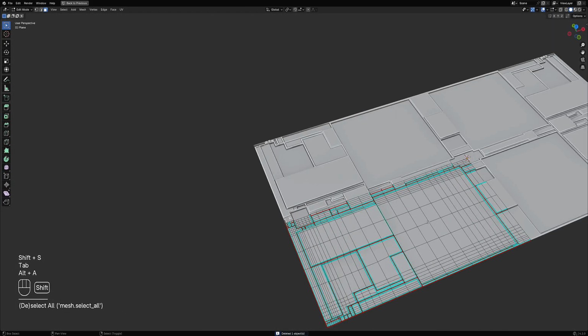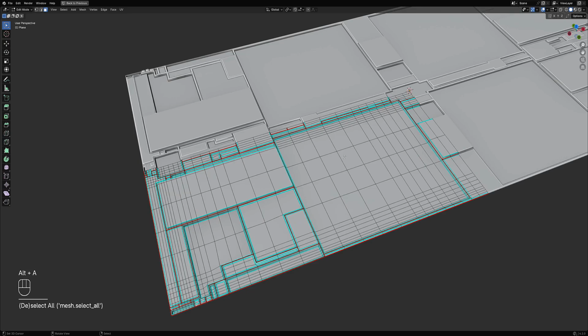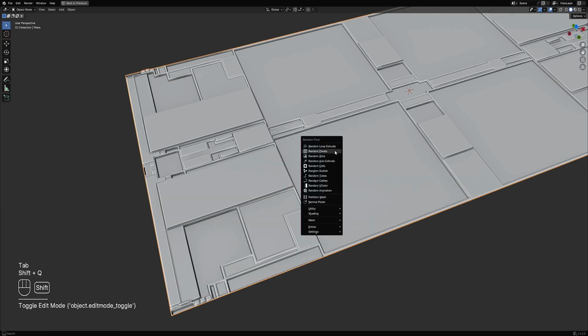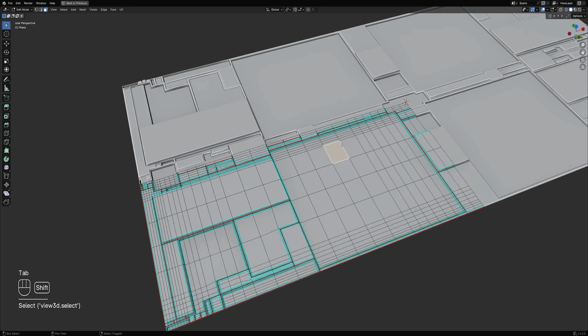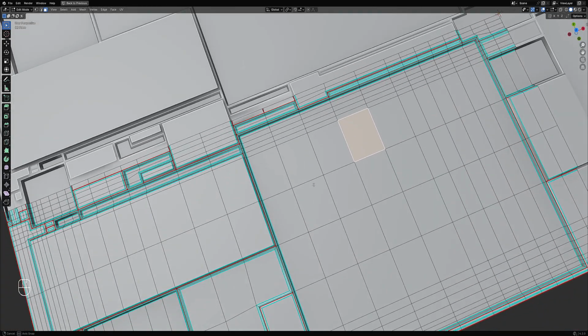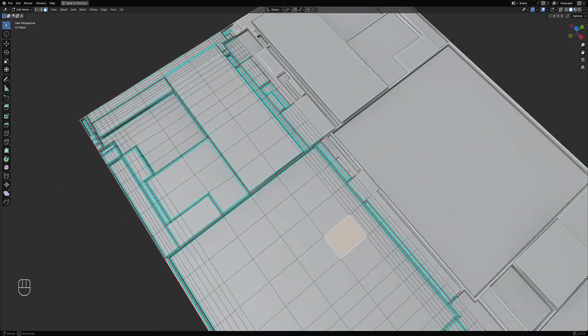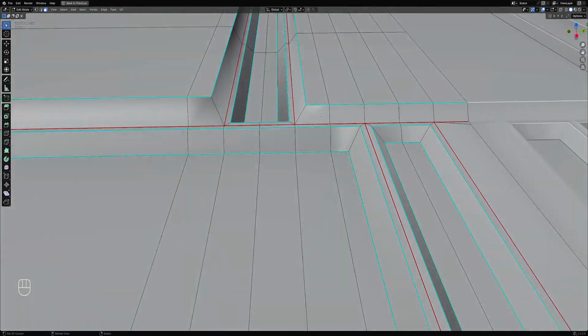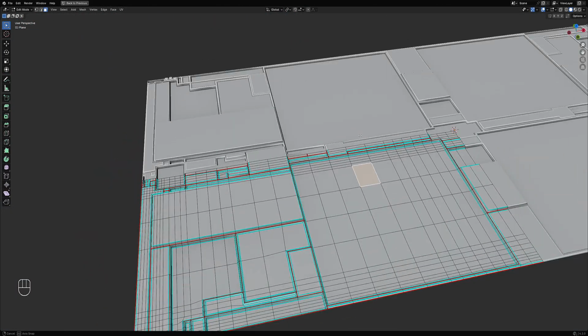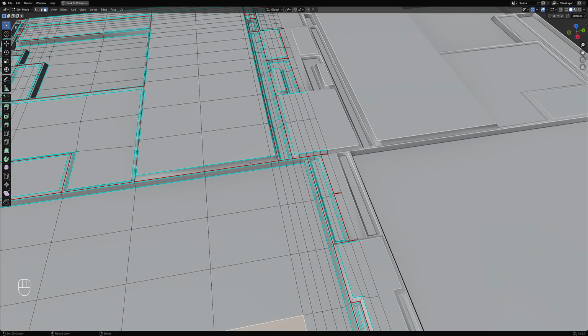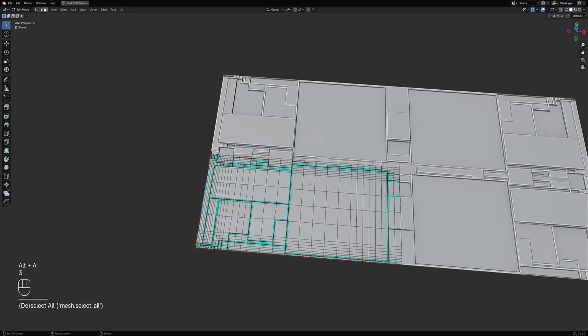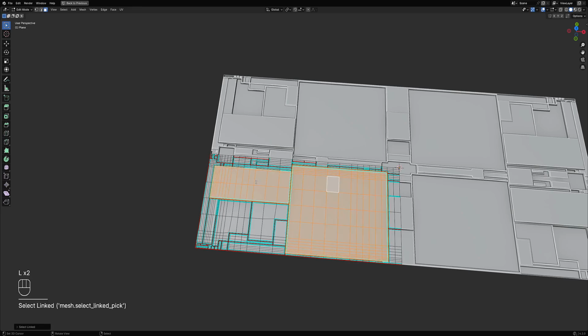And this is true with random panels using the merge feature. The panel island boundaries created from the randomization have been marked as edges whose seams are marked. So you can just go to face selection mode and press L, and it will select those face islands.